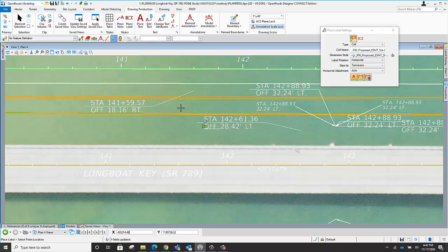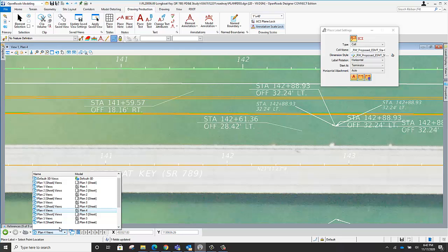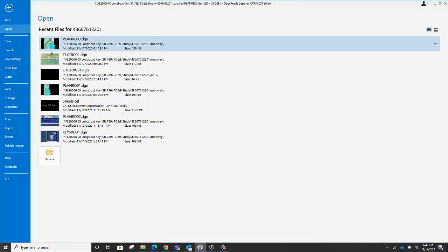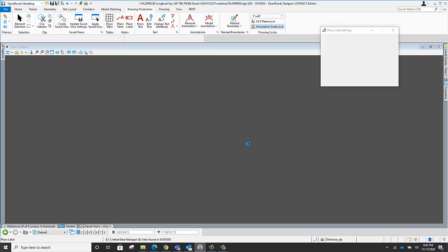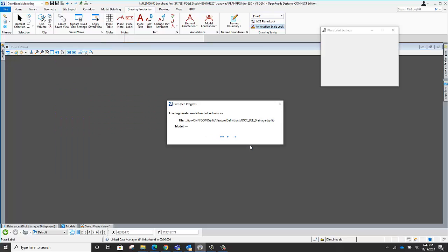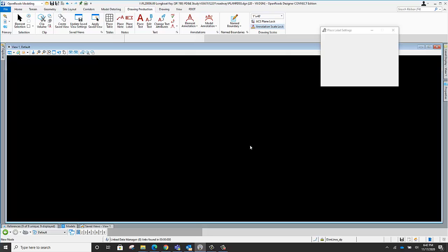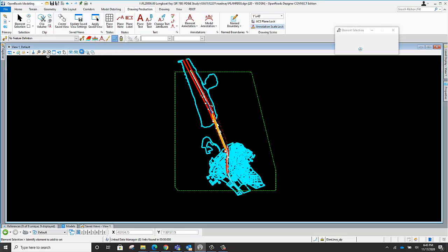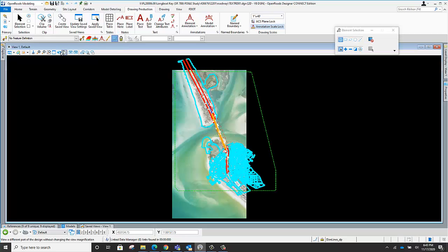Okay, but now these two texts that I just placed here, if I have to resheet, I'll lose them. And to do the labeling, I have to jump from file to file to file, each one. Whereas in my other way of doing it, by getting into the text file, I change my orientation, my rotation, rather.